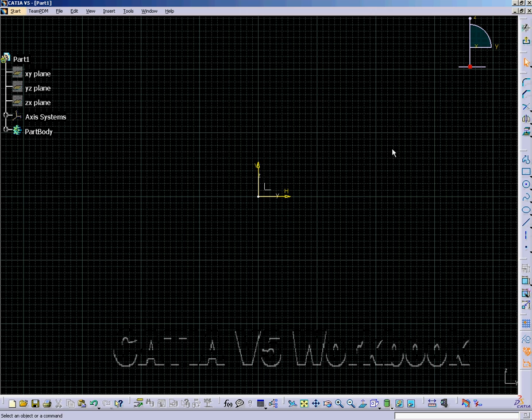Notice right now, being in Sketcher, we are in 2D. We have a vertical and horizontal axis, and we have a grid system. The current grid system is set up in 1-inch divisions with 10 different divisions within that inch. We have numerous tools here. Each one of these toolbars are tearaway tools. They can actually drag them off.